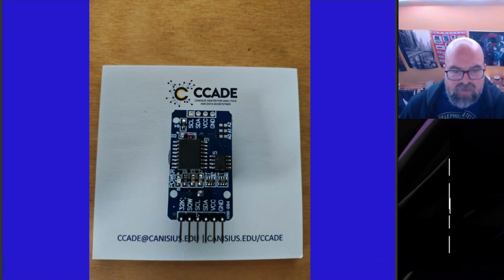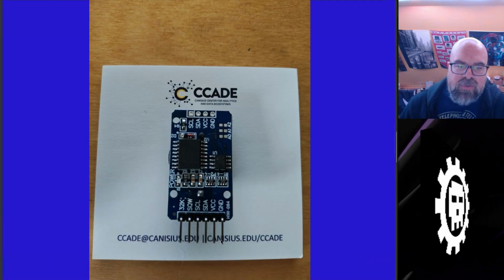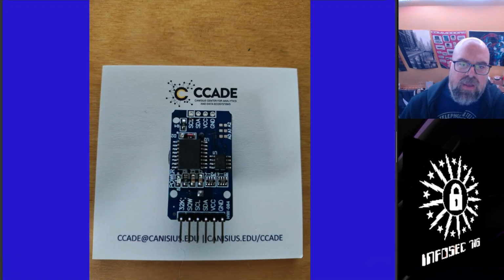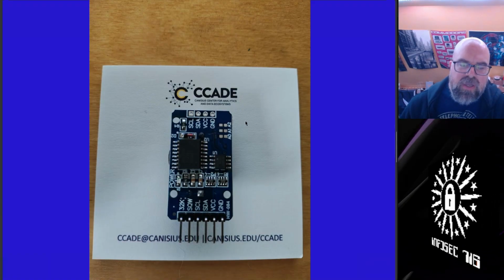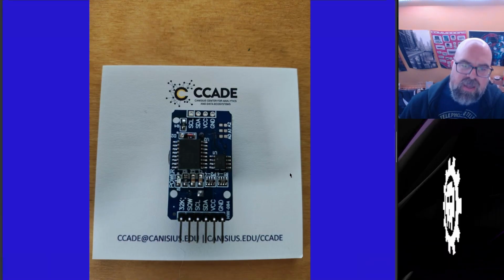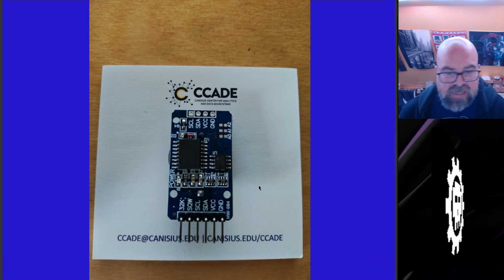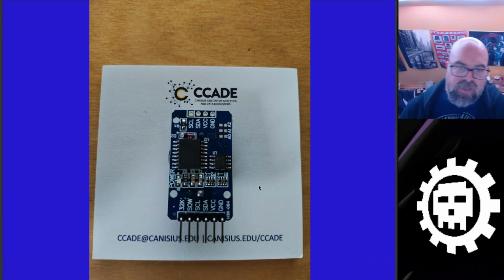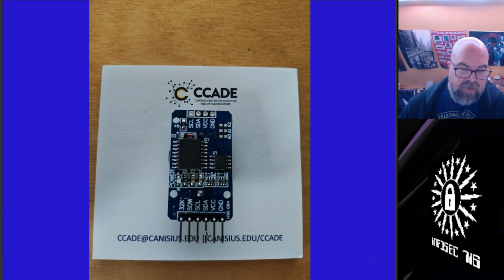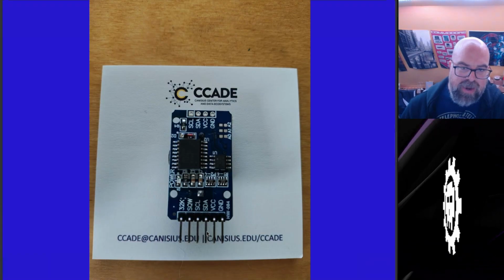So again, just like every other I2C device, we've got a clock, we've got data, we've got power, we've got ground. You'll see these 4 pins are also replicated up here as through-hole solder points for clock, data, power, and ground. These are electrically identical. You can connect either one of these to your circuit, whatever works better. So if you're soldering this in place, if you have some device that needs a clock that needs to be portable, you can use these through holes and solder in whatever leads you need. If you're using it with a breadboard, which is what we're going to do in this video, you can use these pins and plug it into your breadboard and wire it up that way.